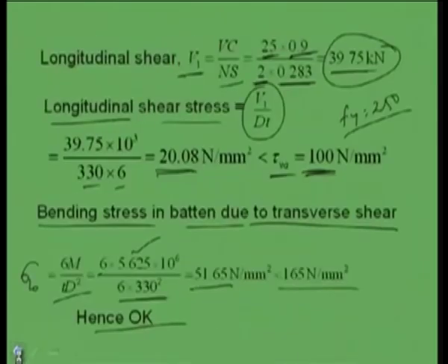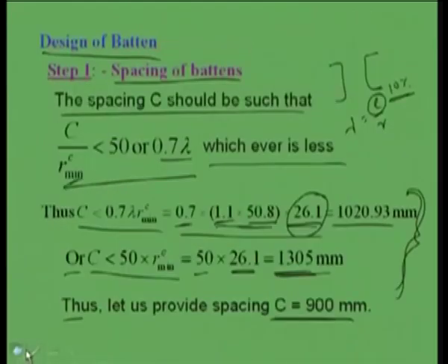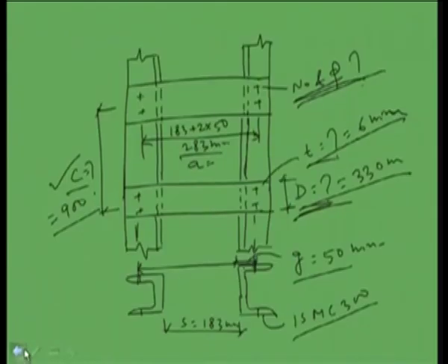So, if we see now the details of the design, we will see that here the number is 4 numbers of 25 diameter power driven shop rivets, and 4 numbers means, say suppose this 4 let us provide, and this rivet distance will become 80 and this edge distance will become 45, right. So, in this way we are going to get all the details.